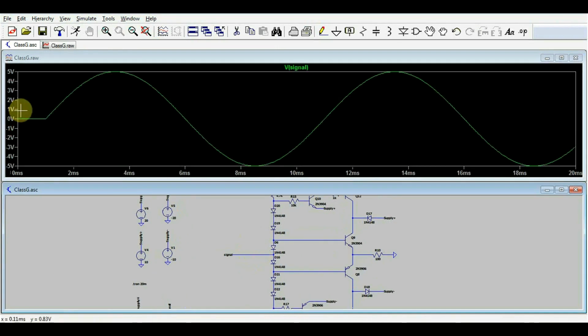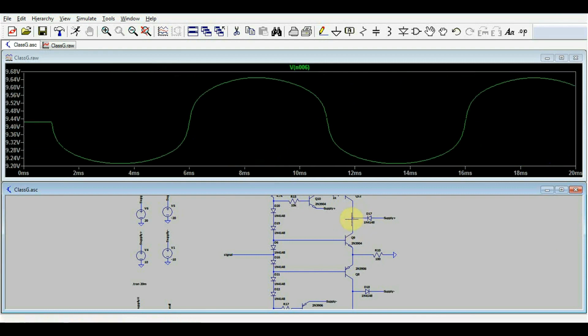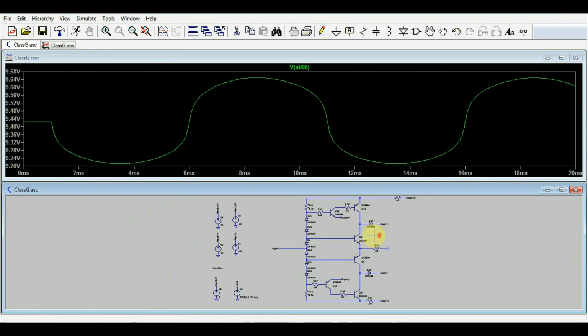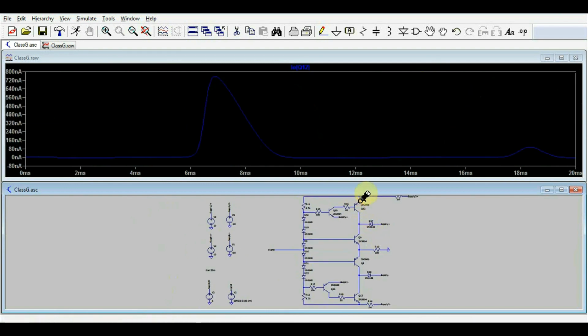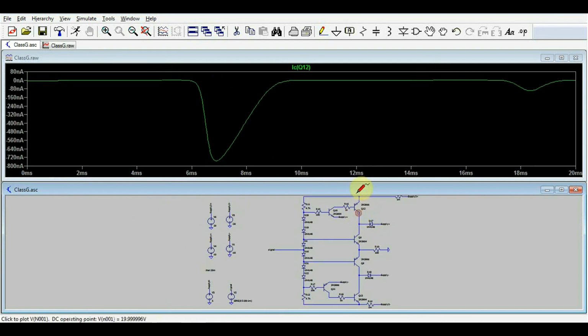Right now I'm driving with a small voltage, so plus minus 5 volts. We have the same thing on the output, so the amplifier is still amplifying. And if we look at the supply of our high side transistor, we see it's around 9 volts. So we have our 10 volt supply minus what we have as a voltage drop on our diode. There's no current going through our high side switch. Well, there's around a few hundred nanoamps, but that's just because I made a very simplified circuit here.